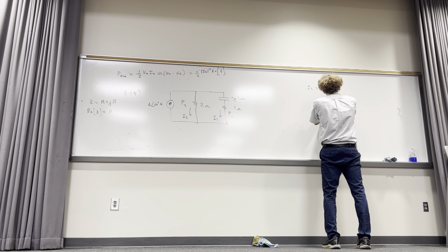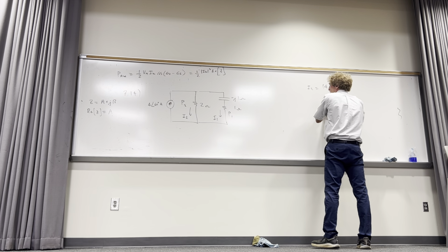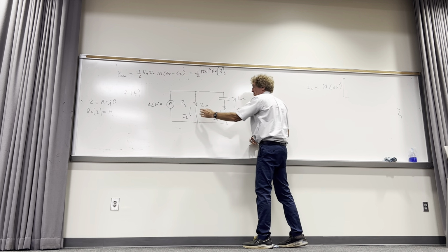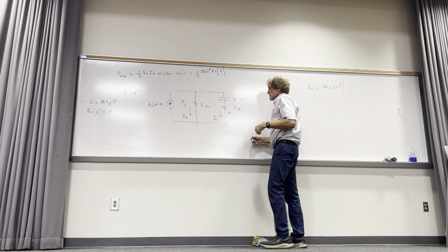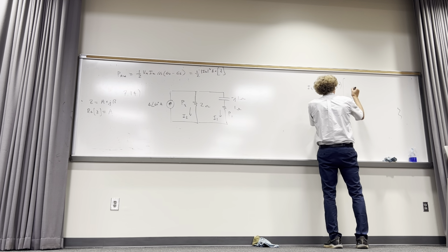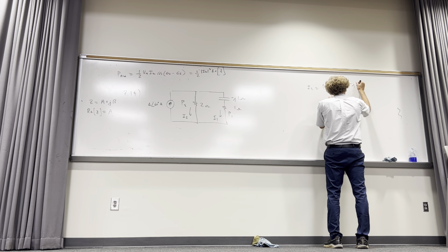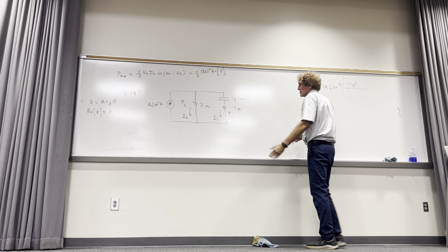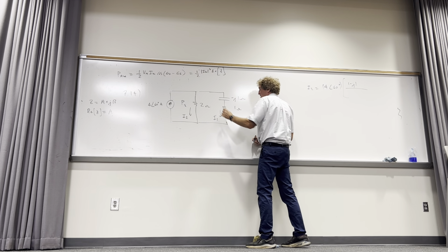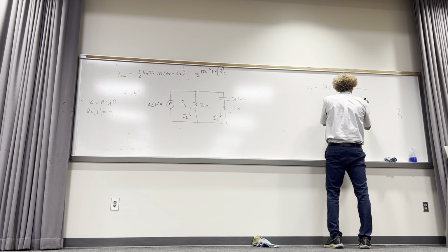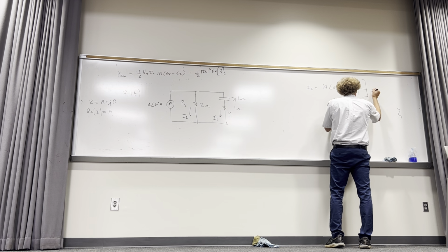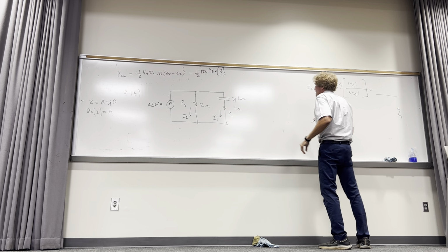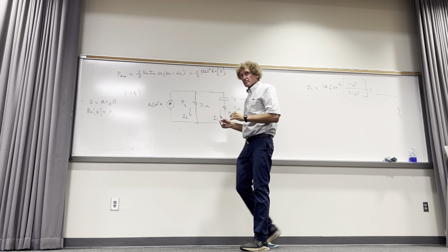Then it's going to be times the opposite impedance. Remember, if you want the current here, it's always opposite impedance over the sum of the two. And the opposite impedance is 1 minus J1 over the sum of the two. 1 minus J1 plus 2 would be 3 minus J1. That would give me a magnitude and angle. You all agree with that?